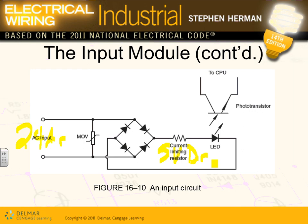You put a current limiting resistor, and then you put that 5 volt into a diode. Now the diode makes light here. Can you guys see that? When the diode makes light, that light will be picked up by a phototransistor, and the phototransistor will give a 5 volt DC into the CPU. Any comments, guys? Any questions about how the input is isolated from the CPU for safety?